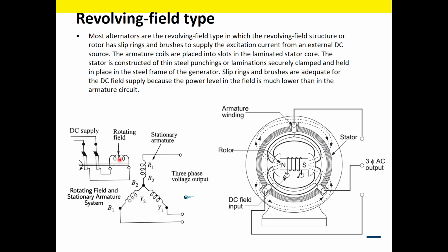Now just remember, all it needs is a DC current going through it, because the polarity of the rotor is going to stay north and south, and we're going to rotate it at a specific RPM. Now we have a DC supply. Again, we have two slip rings, but as you can imagine, the current doesn't have to be that high if we have many turns here.